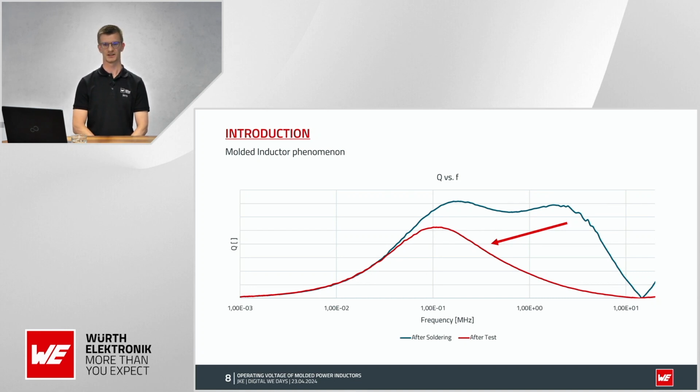And especially at high frequencies, this change is very dramatic. So if we take a look here, maybe at 1 megahertz, which is a typical switching frequency, the Q value change is very dramatic.